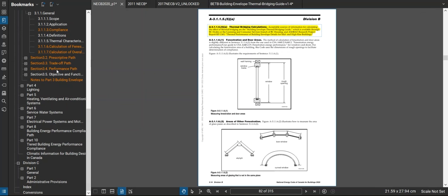And so I guess that's why a lot of the buildings are being done through the performance path, and I believe a lot of the makeup. So yes, the architects, the design community has increased the insulation because of the energy code. It's still not quite there, so I think the rest of it's being made up in the mechanical systems for the most part. Because I'm still seeing buildings with well over 33% glazing as well. So I think when you get into the energy modeling, probably a lot of that's being made up through mechanical systems exceeding the requirements of the energy code.